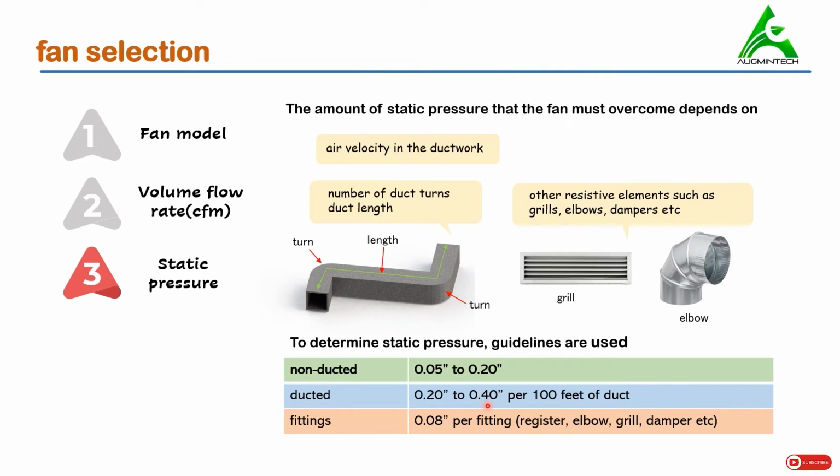These values are specified by the manufacturers, so it is always advisable to use the accurate values provided in the fan catalog. Now for fittings, these values are also provided by the fan manufacturers. Generally, we'll be taking the value as 0.08 inches per fitting.